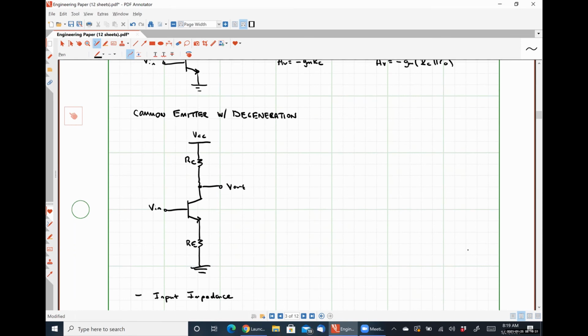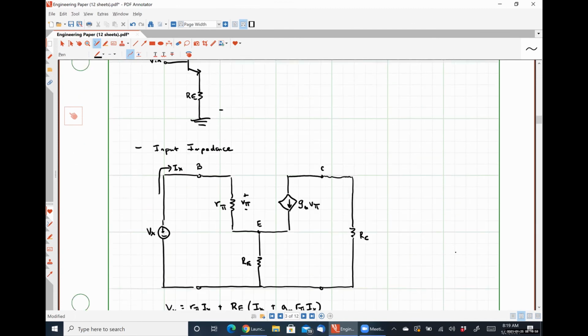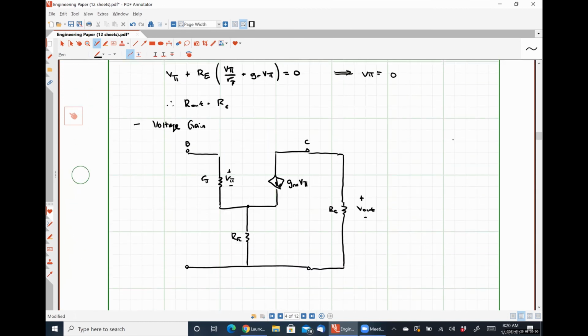with this statement, right? So small signal model, V out, or large signal, V out is a potential difference between the collector and ground, right? Small signal model, our VCC becomes short circuited. So that's the exact same thing as this voltage, which is the voltage drop over RC. So I just want to be clear about why I'm saying that that is my output voltage. Let's see what we got here. Here's my input.